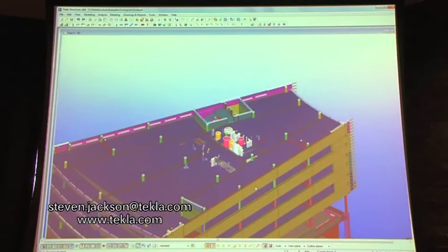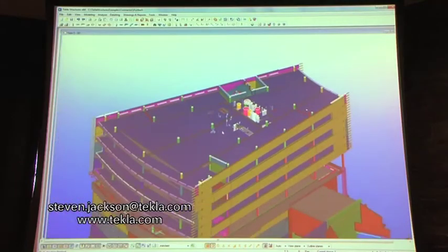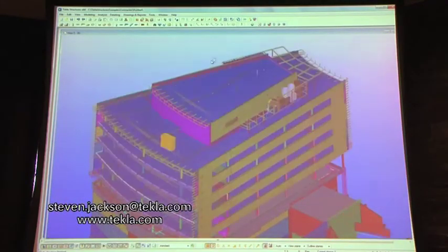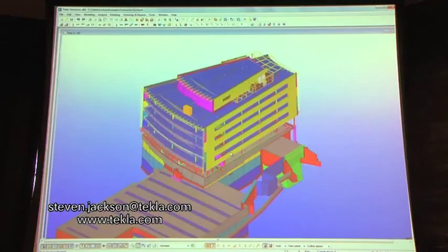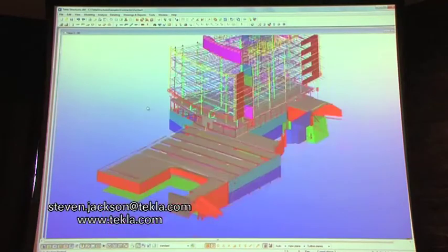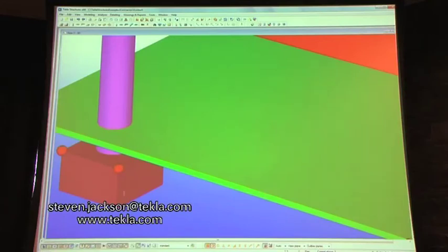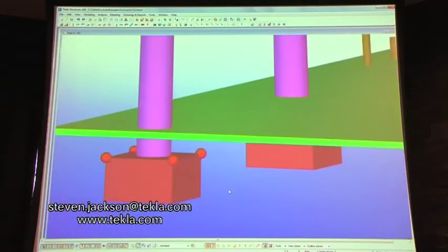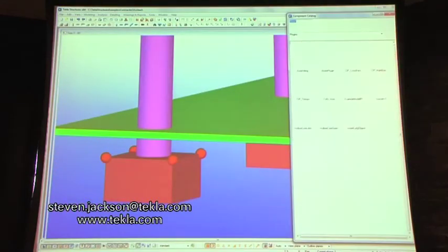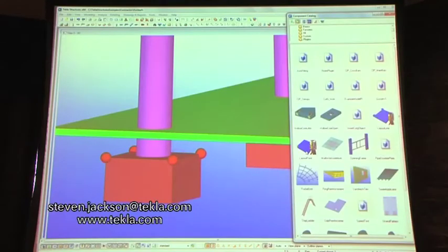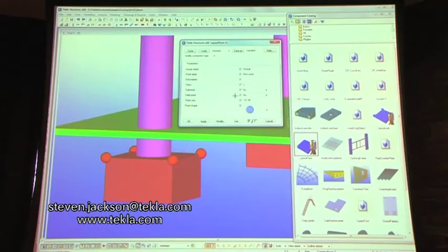Okay, so what we've also got in Tekla Structures, like Dave was talking about the extras, we're talking about the Trimble information. So if I come down here, you'll see there are some points in there. See the points on the foundations? If I go Control F into the plugins, we can actually apply layout points into the model. So we can place them where we see fit, where the foundation should be.